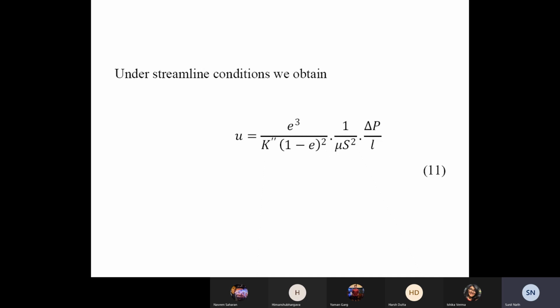As the flow rate starts to gradually increase, the void volume in the bed starts to increase, and there is an incipient point when the bed is no longer packed, and that is then called a fluidized bed. For that we need to do the force balance afresh, and then we will get similar equations, a little modified from what I have given you, and we will have a new set of log coordinates plot, and on the same lines we can find everything about the fluidized bed.